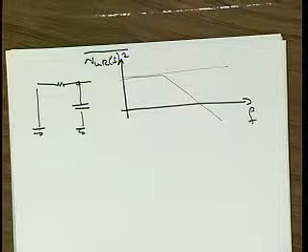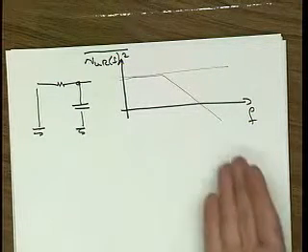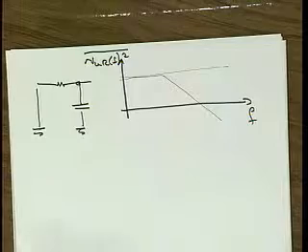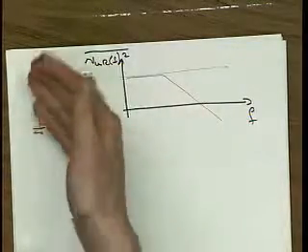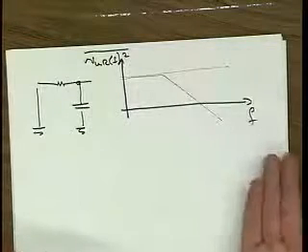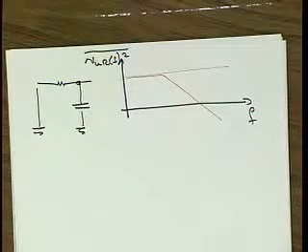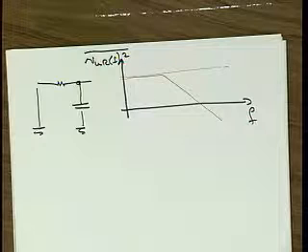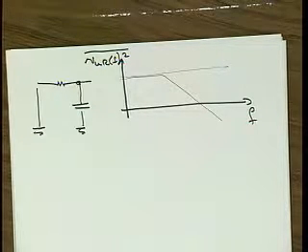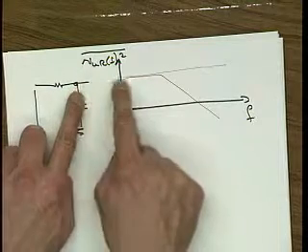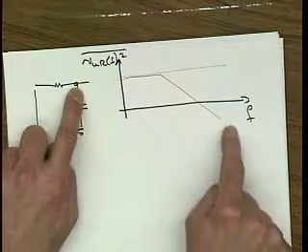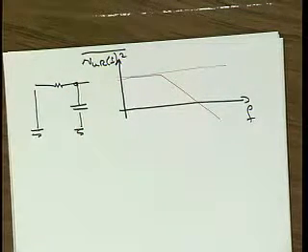So in this case, it has this low-pass characteristic simply because the circuit filters its own noise and gives it the characteristics of the circuit. Okay, so we know that. While the switch is closed, the spectrum of the signal here is continuous, and it has this form.